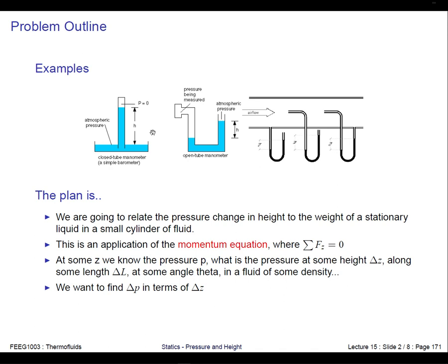Imagine you have a tube of water under the liquid with no air bubbles in it, and you carefully turn it upside down so the open end of the tube is under the level of the fluid and the closed end is above it. There's no pressure in this region, it's a vacuum in this gap, and there's atmospheric pressure in the rest of the atmosphere.